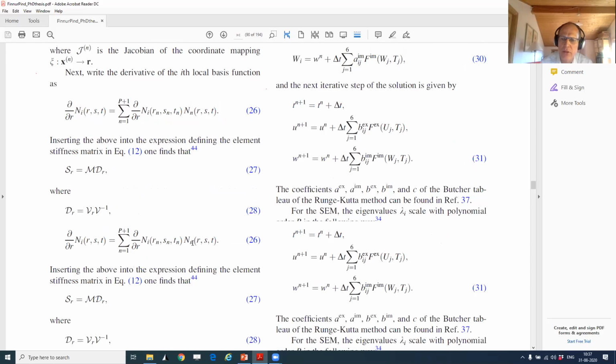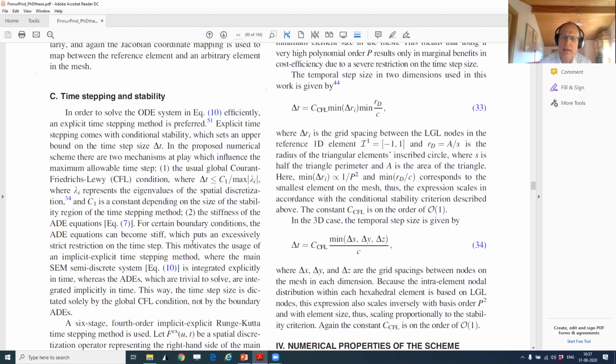But I'm a little bit curious. It would have been quite nice to see the time domain behavior, so the impulse response of such modeling, because it can happen that we find some frequency domain expression that works perfectly fine to use in the frequency domain. But if we want to convert it to a time domain signal, then we have to make sure that it behaves well down to DC and up to half the sampling frequency. And we just have to assume that that is the case. Can you tell if you have seen any kind of material models that have caused such problems, or has it been completely unproblematic?